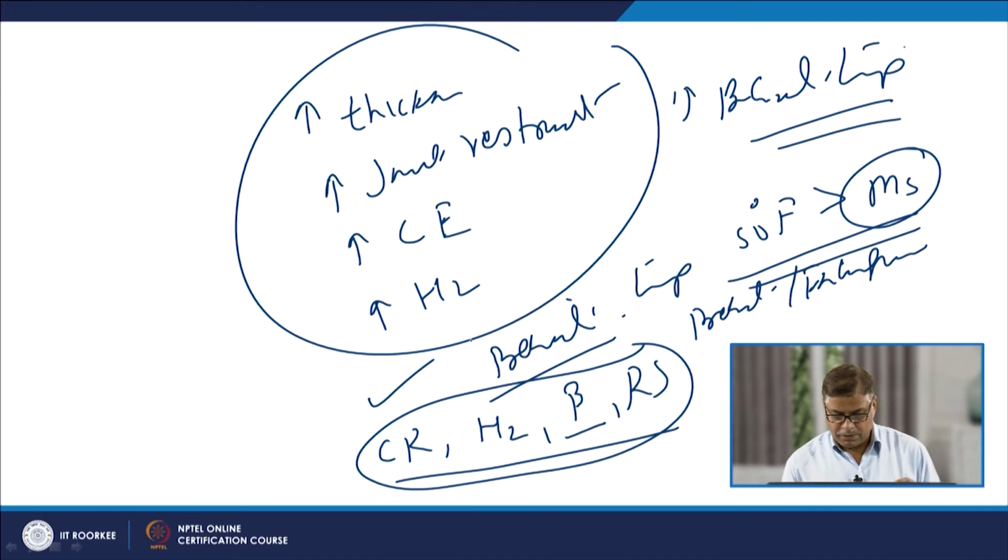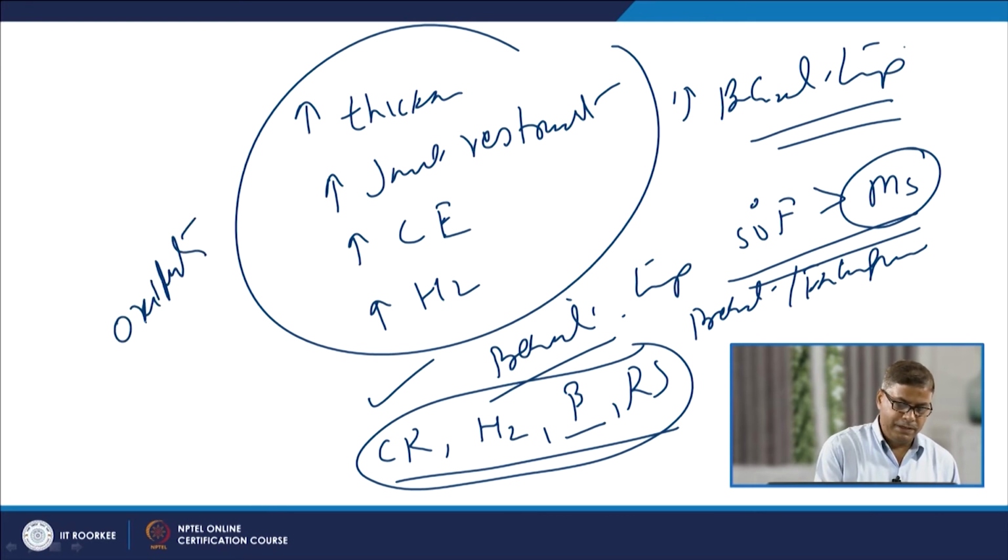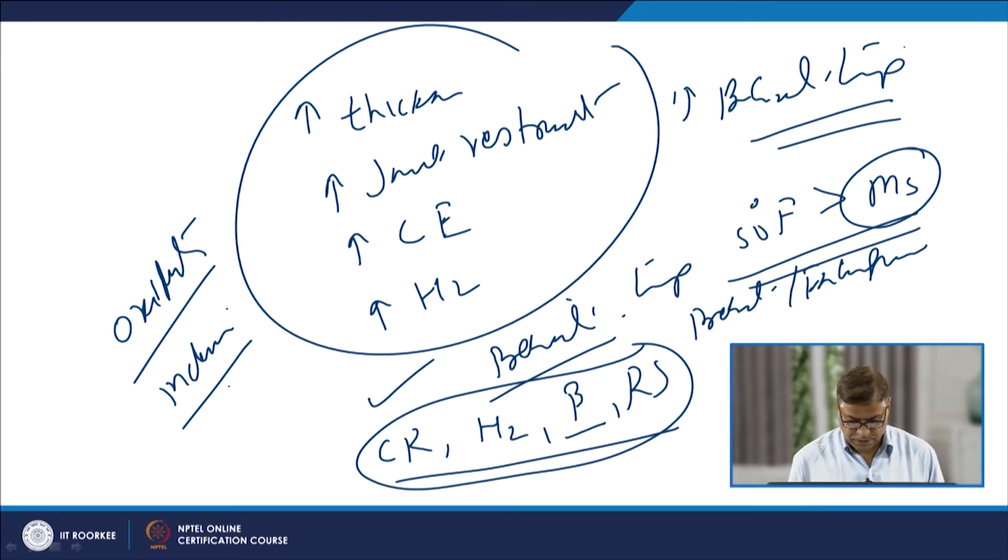However, there is another adverse effect related to the higher preheat: oxidation will lead to the formation of inclusions in the weld as a discontinuity, and dealing with the hot plates will make the job of welding more difficult for the welder.